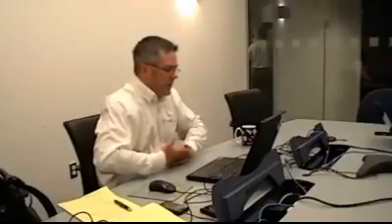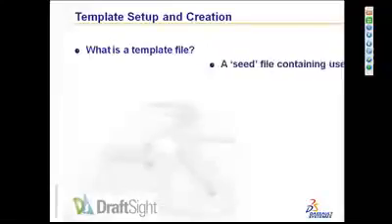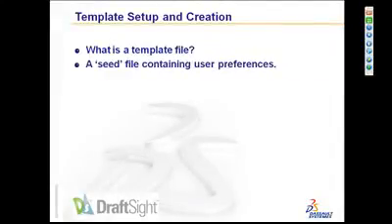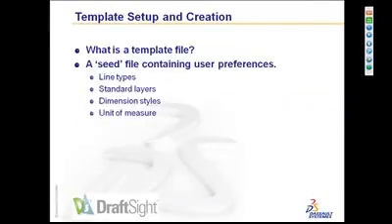So, template setup and creation. When we decided to put this series together, I thought I could ease into it with a topic that a lot of people either don't understand or aren't familiar with. I've done some training throughout the country and even in Europe, and I find that most times when I go into someone's business, they don't take the time to set up a template file prior to creating their work. And I think it's important. The template file is just a seed file that contains user preferences. These user preferences can be line types, layers, dimension styles, units of measure, blocks, even drawing formats.